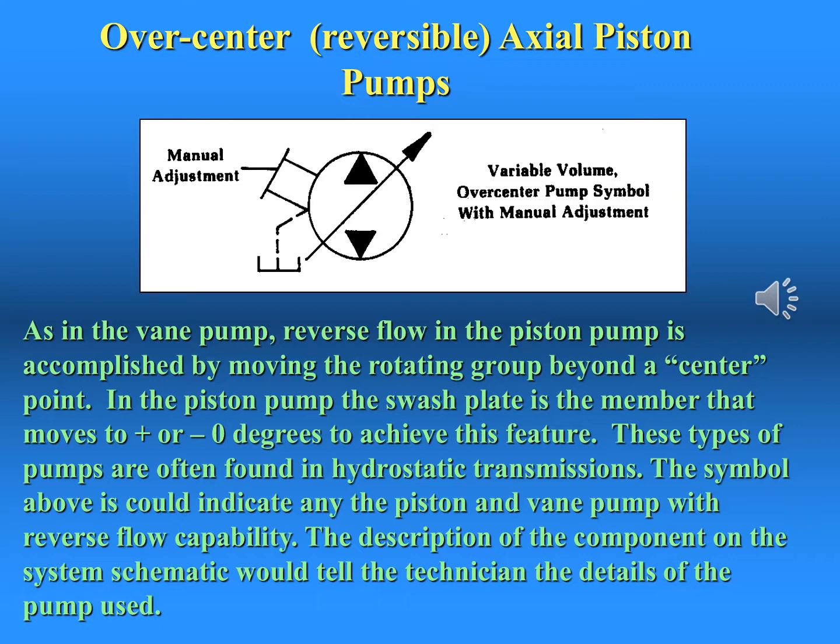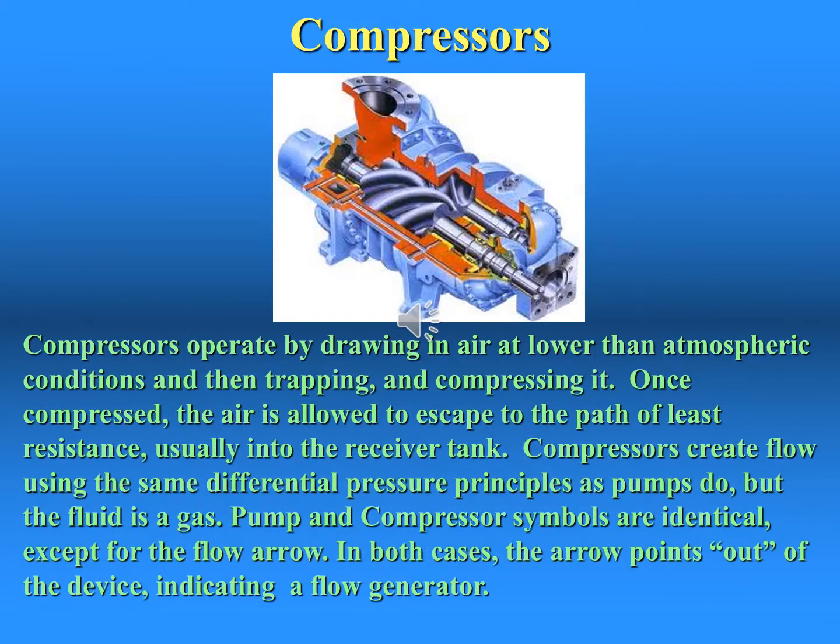Piston pumps are often used for this purpose, which provide two directions of fluid movement accomplished by a swash plate which can move from one tilted extreme to the center position and to an opposite tilted extreme. Control may be provided by an external mechanical device.